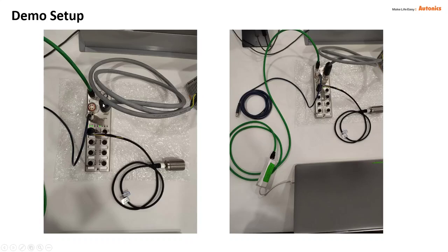Then this cable we see, the gray color one, is the power cable which is supplying power to the IO-Link master card. It is going to supply the sensor and the actuator power supply. Then we have over here PDCT cable. This cable is used for communicating Autonics ADIO IO-Link masters with the PC on the IO-Link software. So for maintenance purpose, if you want to check the port configurations, we can use this PDCT cable for checking the same.